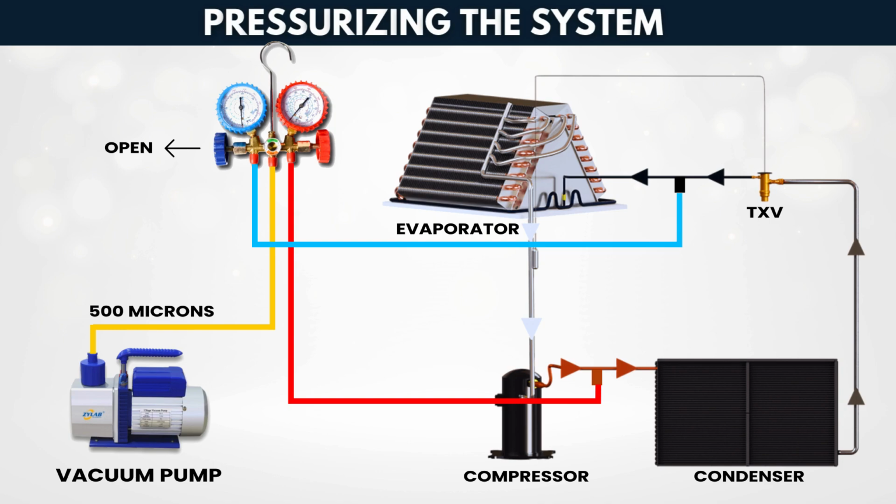If your pressure drops too quickly, double-check all your hose fittings and valve connections. If it drops slowly, it could be due to temperature changes, very small leaks, or trapped air. And if your vacuum doesn't reach the target micron level, you may still have a small leak, moisture, or a blockage. In that case, repressurize with nitrogen and test again before re-evacuating.